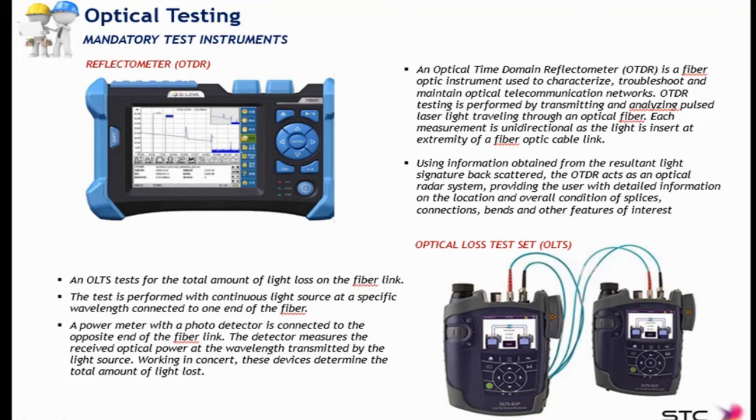The OLTS, the optical loss test set that you have down here, is actually measuring optical power level. This equipment typically is two different devices. One of them is a laser source. The other one is an optical meter. On this picture, you have both functions integrated in the same device, but these are high-end devices. The high-end devices come with more features, but they are not really required for STC testing purposes.